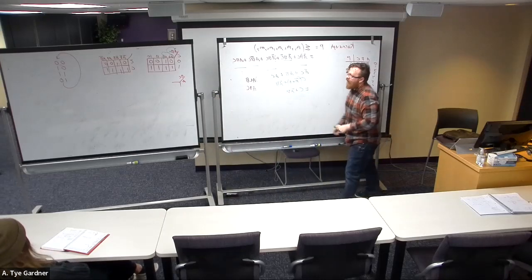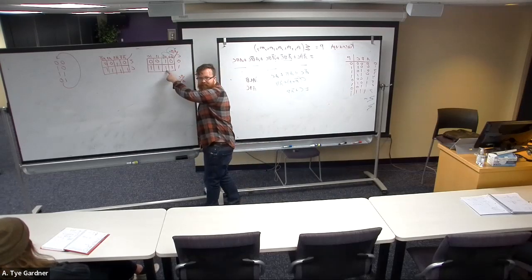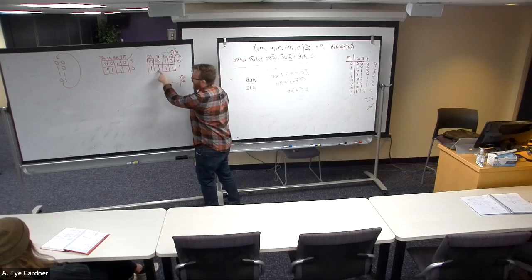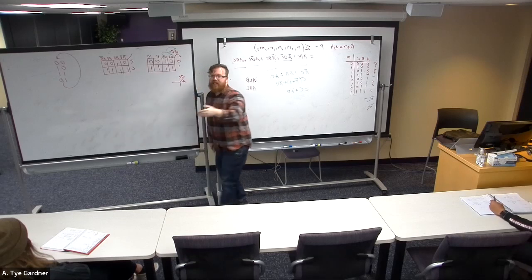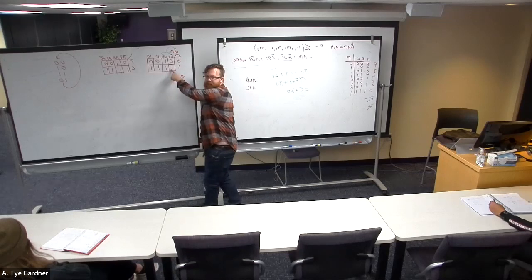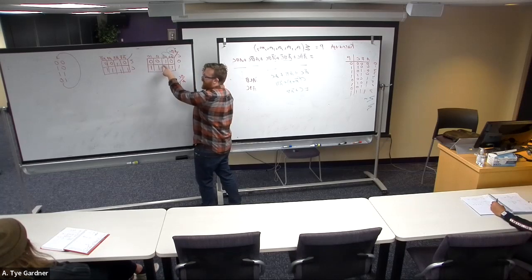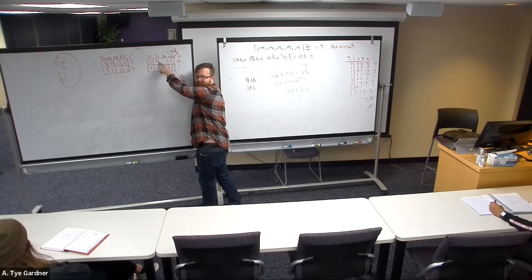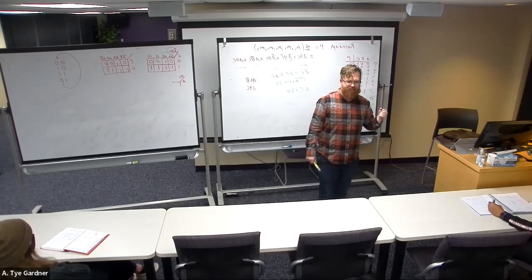Now what this is saying is this one and that one are logically adjacent. This one and that one are logically adjacent. And this one and that one are logically adjacent. And guess what? Because Gray mapping is circular, this one and that one are also logically adjacent. It wraps around. Logical adjacency does not work diagonally, right? Because this one and that one are not logically adjacent, that means they can't simplify. We know they simplify if they are logically adjacent.